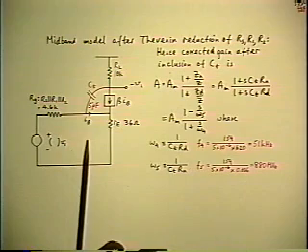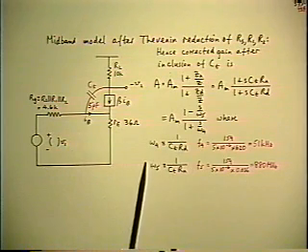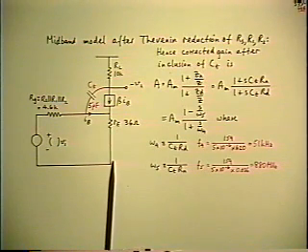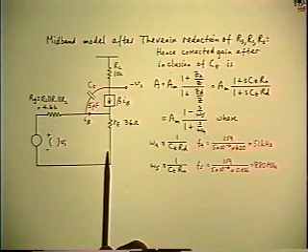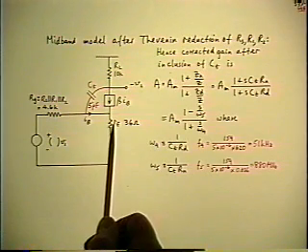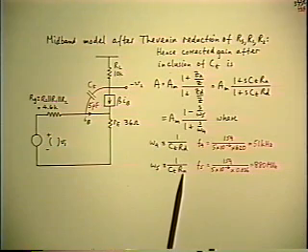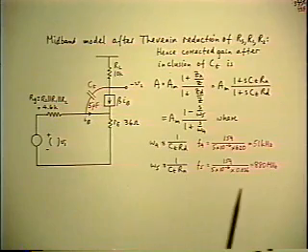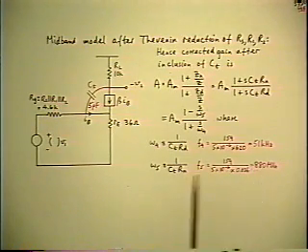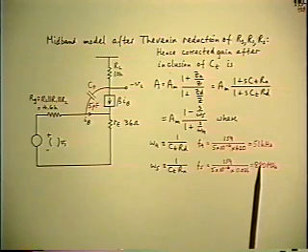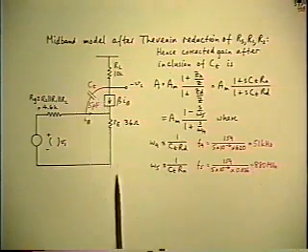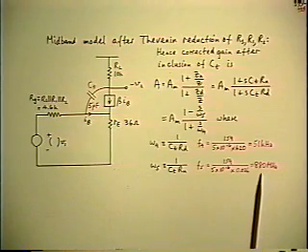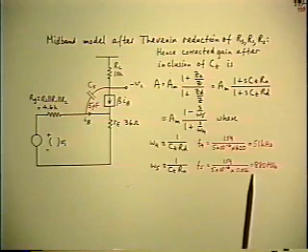That's one reason. Another reason may be, suppose you have an unbypassed emitter resistor down here, like the 2.2K we've had in the previous examples. It adds directly to the RE, and we already know the Rn is minus Re, and if it has an R in series with it as well, which is 3 orders of magnitude larger, that also brings this frequency down by 3 orders of magnitude. And suppose you have both of those things at the same time, bigger capacitor and bigger resistor, then you may be down into the low kilohertz region.